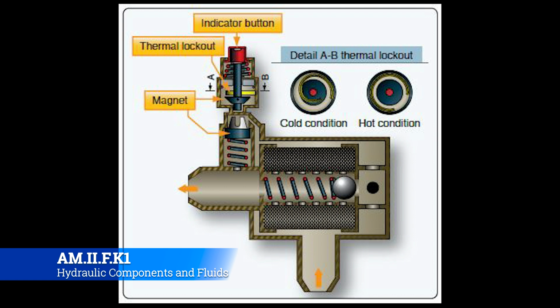Now, there's another scenario where it doesn't give an indication in the cockpit, and that is meant to be caught on a walk around, either post flight or your maintenance daily checks, or whatever the maintenance system is that's being employed in that particular operation. But these are things that are good to know because whenever you're doing your walk around, you should always put your hand on it and make sure that it's not popped up. Now, the reason why I say do that, it's not because they only come up halfway or anything else like that. It's because if you're physically in the habit of finding this thing, putting your hand on it, there's a very low chance that you're ever going to miss it.